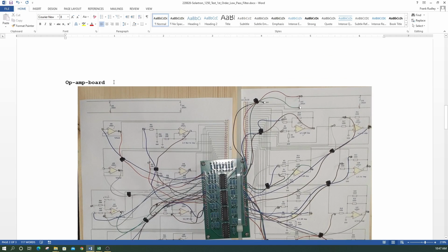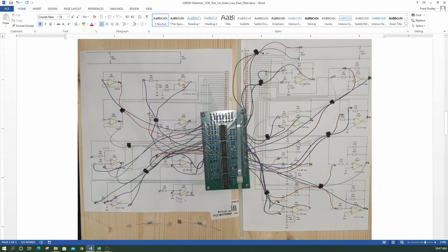So this is the op amp board that I made. It's a general purpose board for lab use. This is something that I put together just to use in the lab, and it has a bunch of different kinds of op amps. Followers come in handy. There's differential amps and inverting amps. I tried to break out this point so I could add a capacitor to make it into a low pass filter. The differential amps definitely come in handy when you use an oscilloscope, if I need to look at a differential signal,